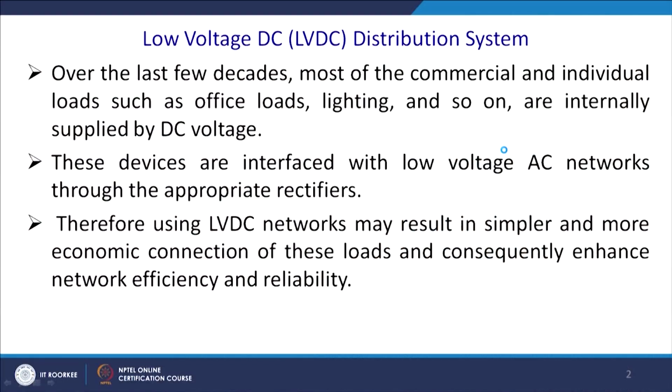So, the issue is that over the last few decades, most of the commercial individual loads, such as office loads, that means desktops, laptops, lighting, these are LEDs and so on, are internally supplied by DC voltages. You may have a big LED TV that is internally supplied by a DC supply, and thus these devices are interfaced with the low voltage AC networks generally through appropriate rectifiers.